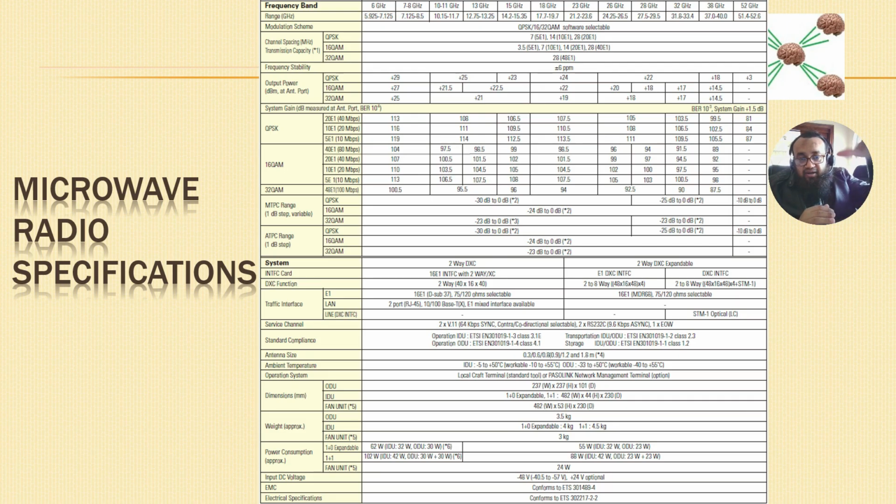Then it will start the modulation to bring it down. Because, for example, if you are in a city and you increase the transmit power because of rain or anything, and it is not automatic, someone manually did it and he forgot to bring it down, then when the rain subsides, your link is still working on a very high power, and it may start creating interference to other links.